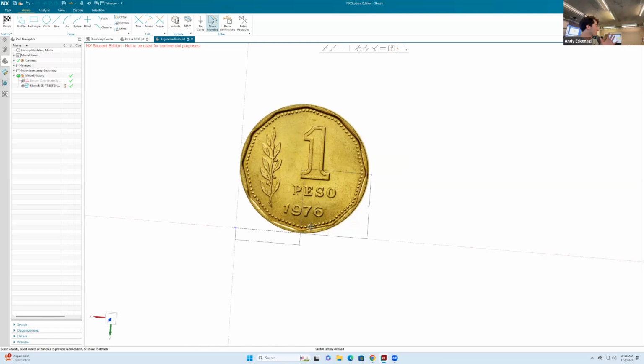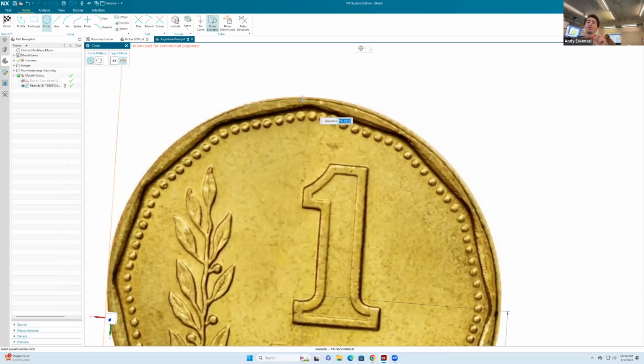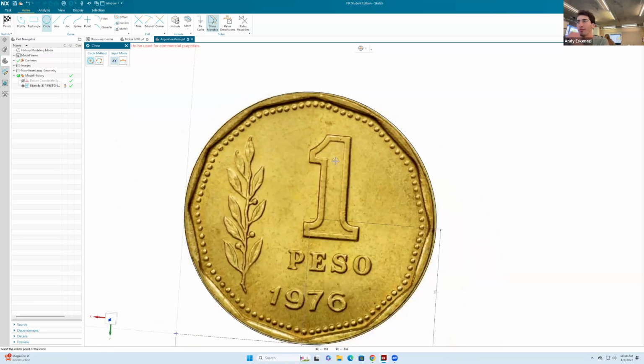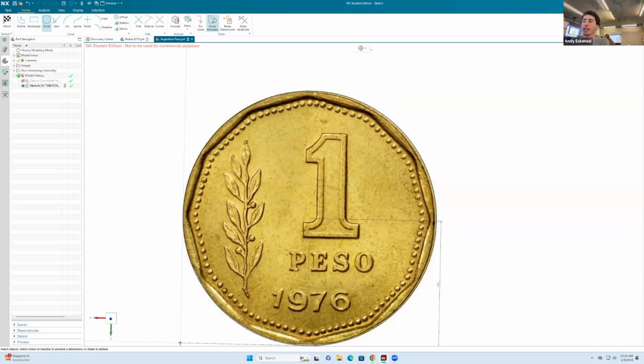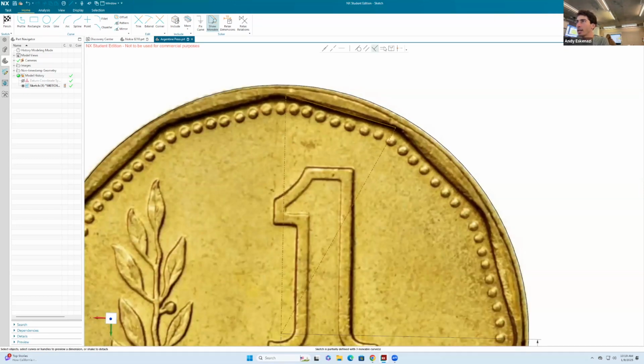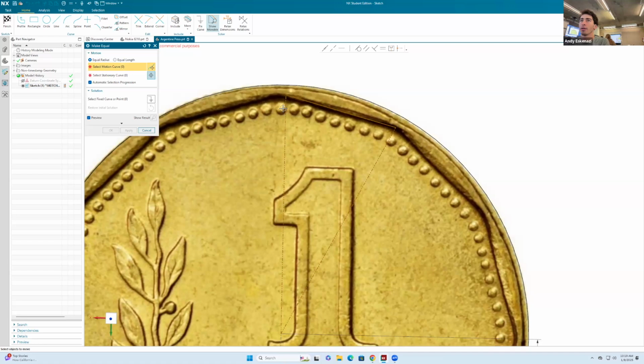So now's the fun part. We're going to start on this sketch making everything, right? We're going to start tracing. So I'm going to start by drawing a circle. Today is the only day that I won't care too much about fully dimensioning things. I want things to look roughly okay. So I did that circle, and then, oh, this one is going to be fun. I'm going to draw a line that goes roughly up to there, and then roughly up to there. I'll make these 2 construction lines, and then I will join them right there. And then I'll click here on make equal, and I will make these 2 lines equal length. I'll say okay.